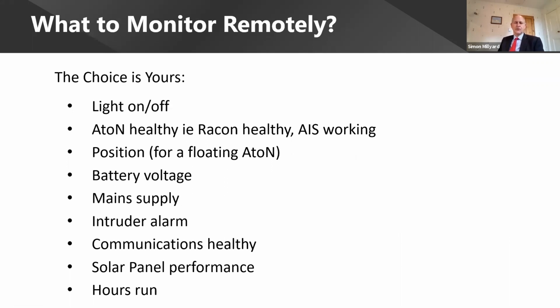And what you monitor, well, the choice is yours, and there's a list of things you can monitor, and on it goes. The more sensors you have on the AtoN, the more you can monitor anything you wish. But it's a question of picking what you think is important, and that will vary, as we will see later on in the asset management component. If the station is very hard to get to, and it's going to cost you $10,000 to get out there by helicopter, then you may be more interested in monitoring in detail so that you know what you're going to be finding when you get there, rather than a station that is half an hour's drive up the road from the office.